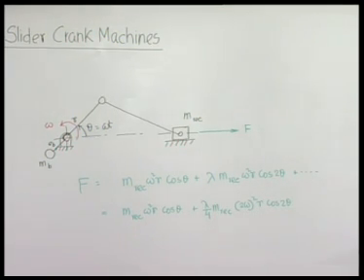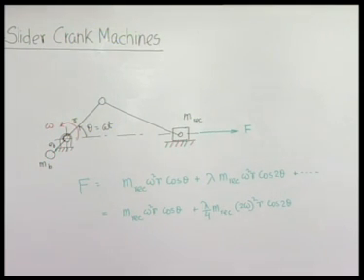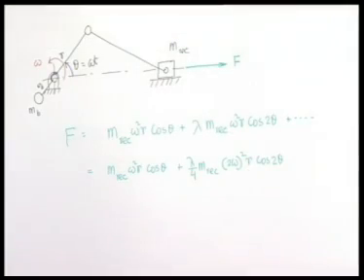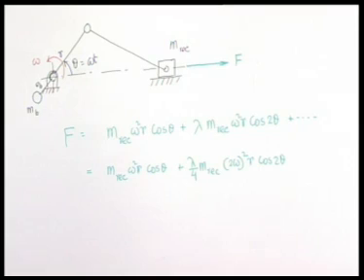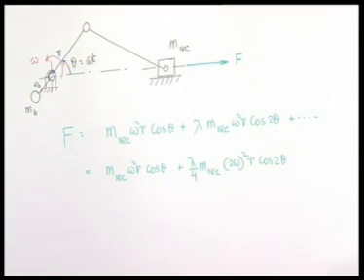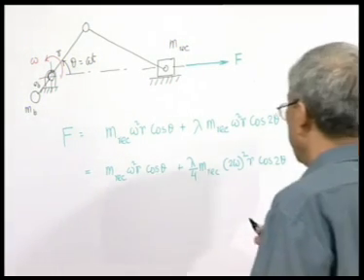But it has also been pointed out in the past that it will be enough in most cases if we consider only up to the second harmonic. Thus, until and unless mentioned, from now onwards we will keep our unbalanced forces under consideration only up to the second harmonic, which we call the secondary.